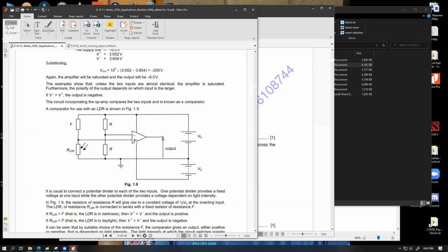So this op-amp, if it can cope with 1000 hertz, will be giving you 1000 hertz of output. So it can handle 1000 hertz. That's a value of its bandwidth. If this op-amp is designed to operate at a maximum frequency of, let's say, 10,000 hertz, which means that if the input signal changes 10,000 pulses per second, this op-amp would be able to handle that information. It will still be able to give out that similar frequency of output. But whenever the input signal frequency goes above that range, then this op-amp wouldn't be able to give you that exact frequency. So it will be lagging behind.